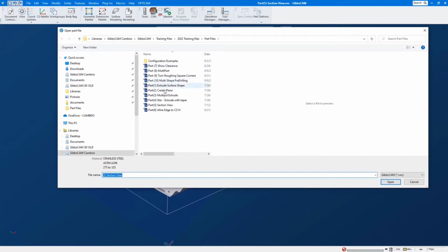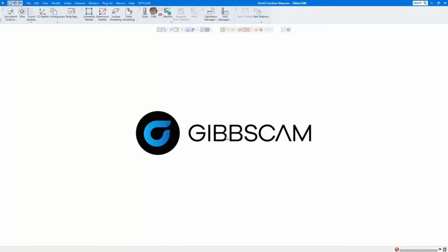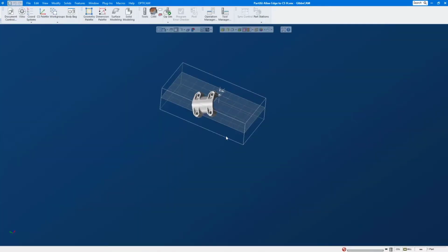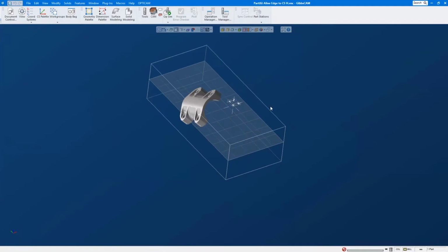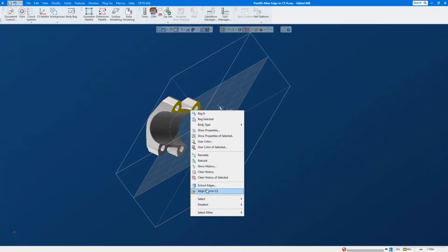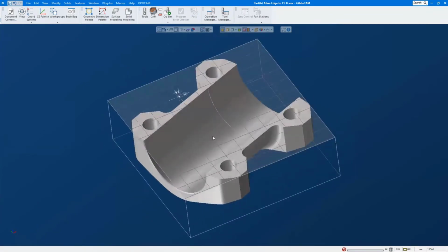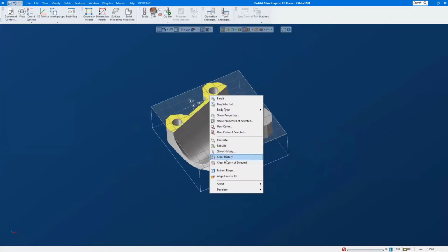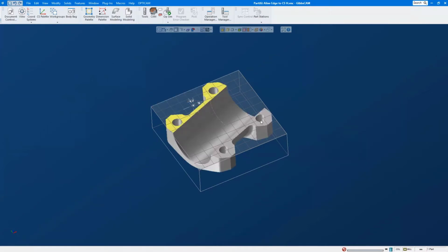All right. Let's look at this one. It's also pretty sweet. Again, I know some of you guys out there build machine sim models and some other things, and a lot of times aligning stuff is really painful. So this is a brand new function that at least it helps. Okay, it gets us in the game. So what I'm going to do is, first of all, select this face and align that face to the CS. And I think we talked about this in our last session. How you can either pick it like that, or if you pick it again, it flips it over, which is kind of cool. So either way.